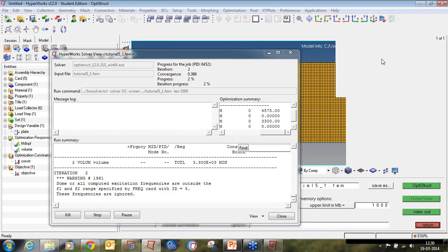In this tutorial, we will review an MBD transient analysis, change one of the rigid bodies to a flexible body, set up and run topology optimization on the MBD system using the equivalent static load ESL method, and post-process the optimization results in HyperView. So we'll start by checking the file type. My file type is HM. So I will open the HM file.